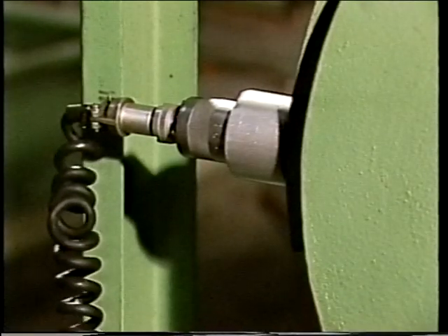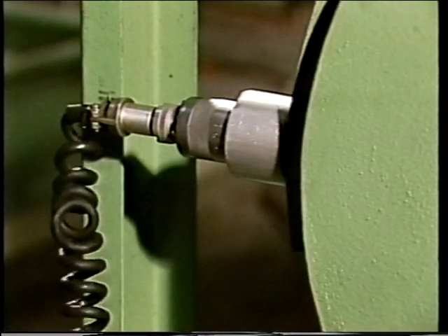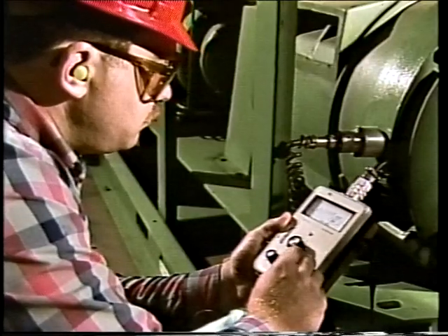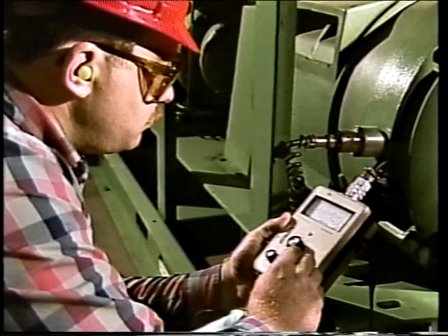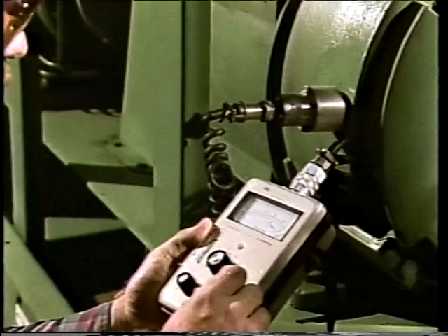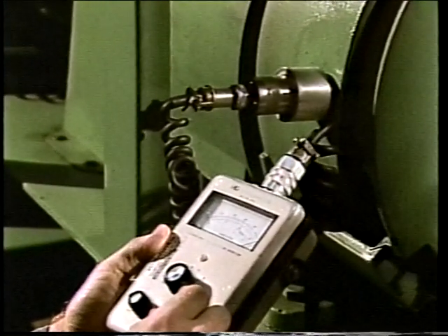Pickup devices, like the ones we saw in the last segment, transmit an electrical signal to some type of vibration monitoring instrument. That instrument interprets the signal and provides the technician with information regarding the nature of the vibration. One type of vibration monitoring instrument is a vibration meter. As you recall, vibration meters provide a general reading of displacement, velocity, or acceleration. They normally do not provide detailed information on any of the parameters. However, vibration meters are portable, which gives the user freedom to move from one test point to another.